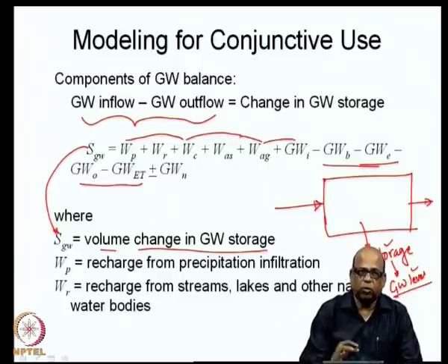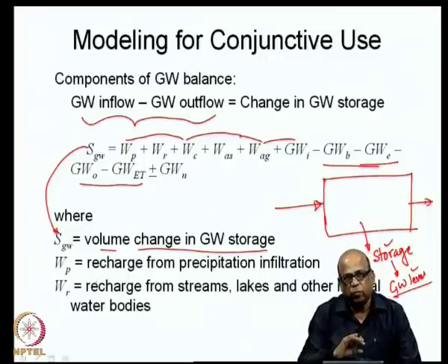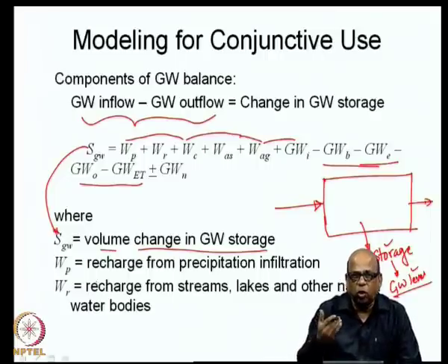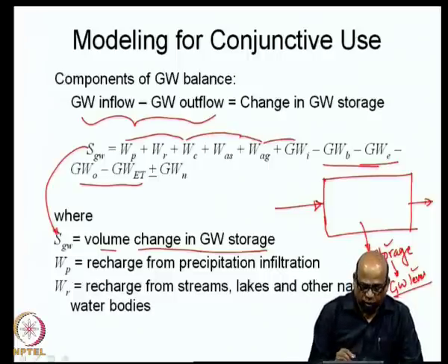recharge. We will assume that all of that goes down as recharge, although you must remember there is an unsaturated zone, vadose zone, in which the flow also takes place horizontally. So, not all of the seepage or not all of the infiltration comes down as recharge, but for the time being we will assume that all of that comes as recharge.